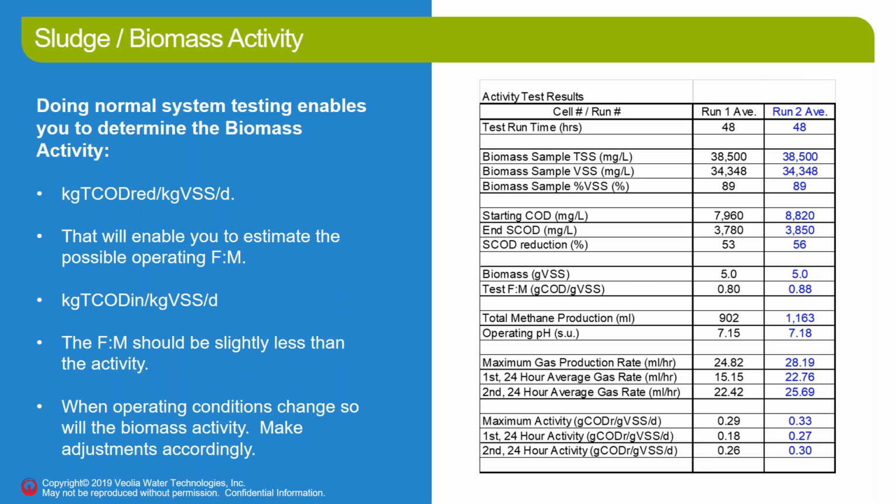If your activity is only 0.5 kilograms of COD reduced per kilogram of VSS per day, you can't put 1 kilogram of COD in per kilogram of VSS because the bacteria won't be able to eat it.